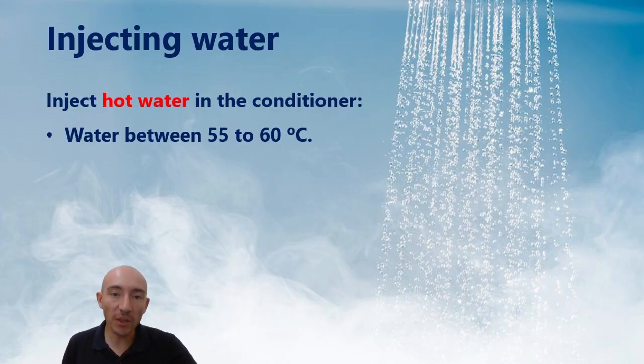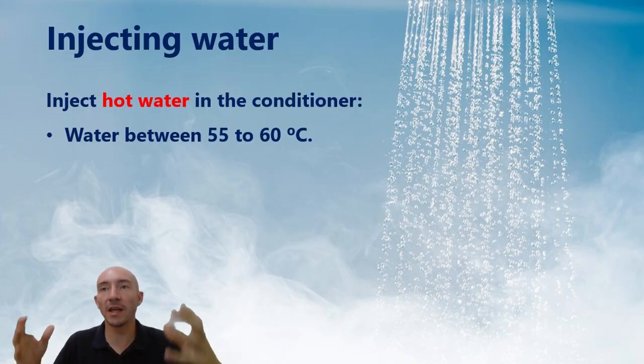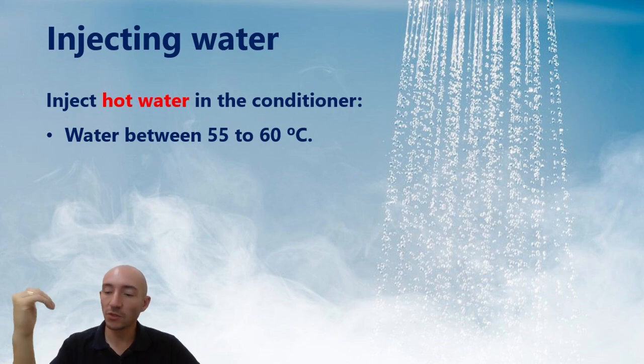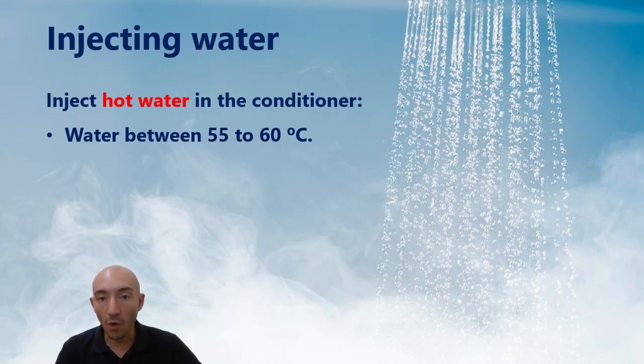Now, if you inject hot water already at 55, 60 degrees, from the moment that hot water hits the mash, it already starts activating the starch, which means that hot water has a similar effect as having a larger conditioner. I have seen factories that made a very expensive investment to install a larger conditioner when they could have made a very small improvement by using hot water.